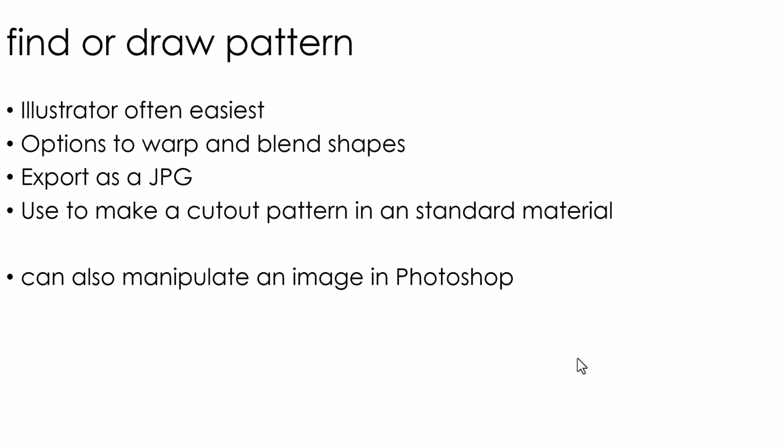You can also take an image of some object and manipulate that in Photoshop. That's how a lot of the wire mesh patterns are created in the Revit asset library. They basically have taken a picture and cut out the background. And it works great. Revit manages to handle that transparency or the cutout very well.